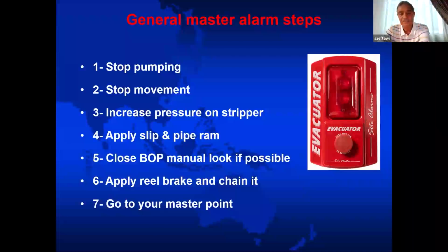And that's why if you need to do a job and you go to Mr. API and say, good afternoon, Mr. API, actually I need to do a job, but the job design will not allow me to put a check valve at the bottom hole assembly. Can I remove it? The API will tell you, sure, no problem. You can remove it. But you have to adjust your rig up and adjust your barrier at the surface that way.